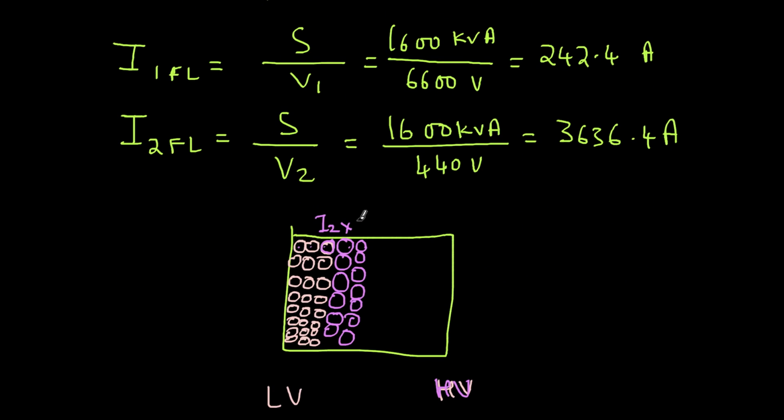Of course I have drawn more, but it is only 15 turns. I can transfer 3 amperes in 1 mm square.